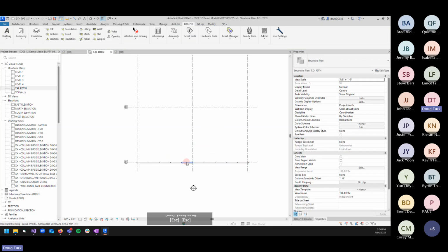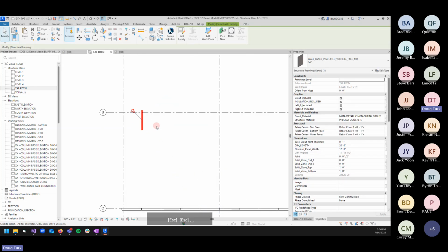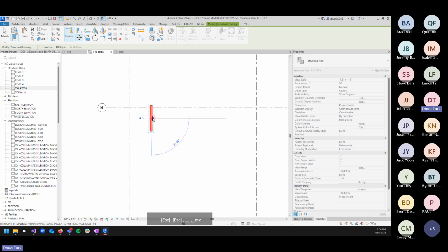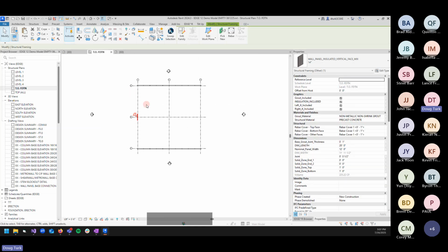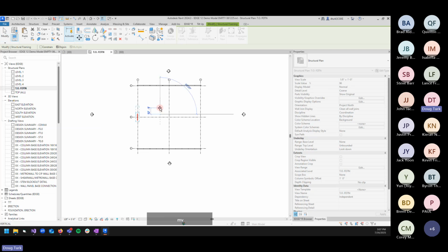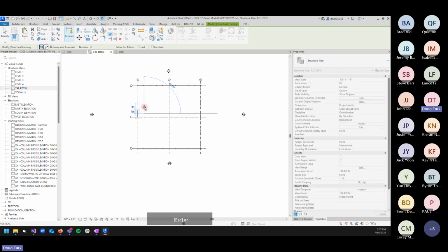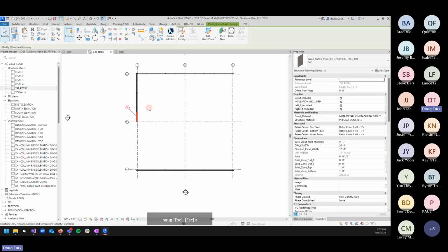This current interaction that I'm showing of arraying these out, of bringing in the panel by panel approach, is something that we're working on in the near future, supplanting with an automatic panelization feature where you would actually model out the full span as a Revit wall and then use that utility to split that into your selected Edge wall family of choice.